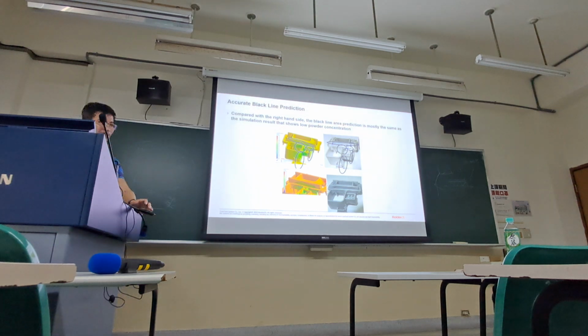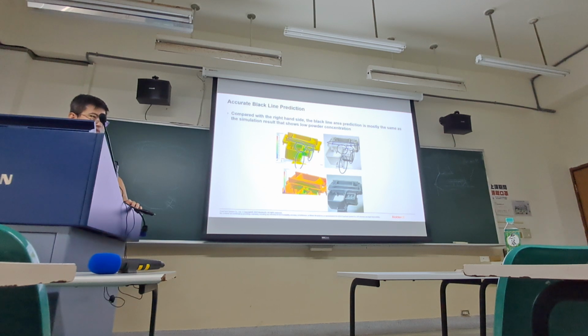Okay. Another question is, since I'm doing MIM, metal and powder, I think it's safe to say that we never have the same size. There's always a distribution. And sometimes these particles might not be spherical, so it's more difficult. Another thing is for your constitutive equation: do your constitutive equations take into consideration whether it's metal or ceramic powder? Because these powders' surface energy is completely different from carbon fibers' surface energy. I don't know if that will affect it.